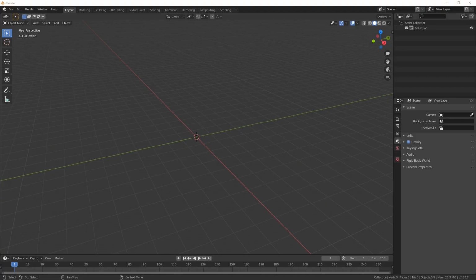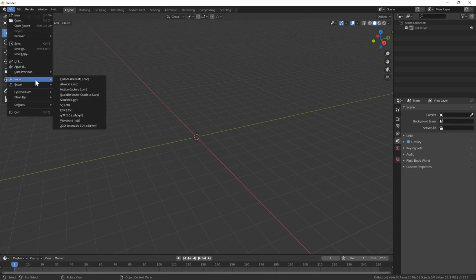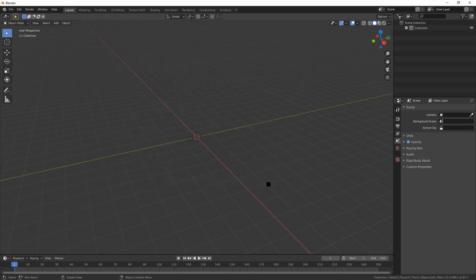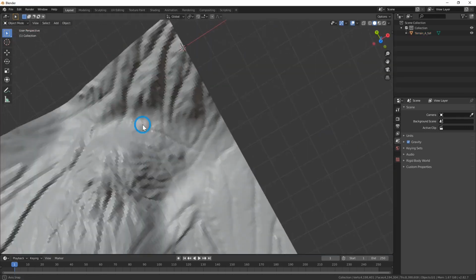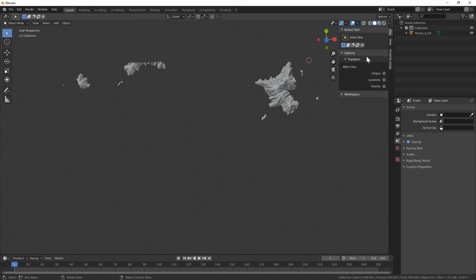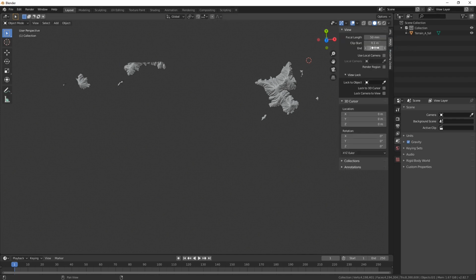Now let's load this OBJ file into Blender. File, Import, Wavefront OBJ, Import. Note that this file is large, nearly half a GB. Simply loading it into Blender takes many tens of seconds. Bring it into view. Because it's so far away, we need to change the end clipping. So press N, click on the View tab, and change the end to 5000.